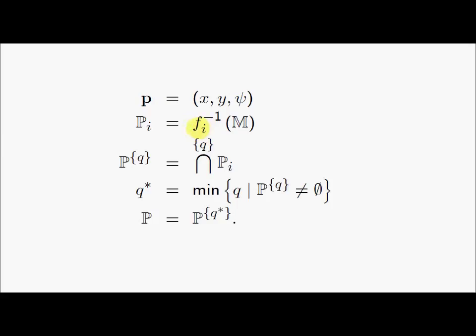So this one corresponds to if I know where my robot is, using the function f_psi, I will be able to compute from M the distance to the map that should be measured by the LiDAR. Of course, in f_psi you have the two other Euler angles that do not correspond to psi, the roll and the pitch.